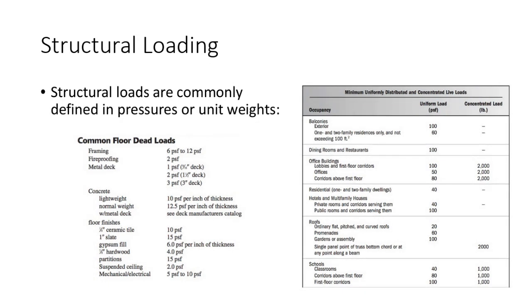Why is that? Well, think about what happens in schools when the bell rings. What happens when the bell rings? The hallways fill up, and the hallways tend to have a higher density of people and loading than the classrooms do. So the hallways see a heavier load. Plus, in emergencies and things like that, they're going to see a lot of loads. So that's why those are heavy.